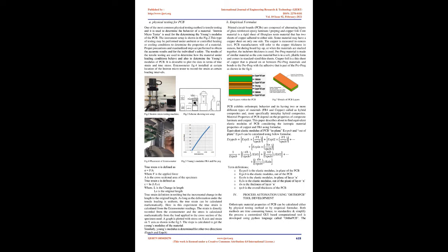The results of the tensile testing are used to determine how the material behaves under loading conditions and also to determine the Young's modulus of PCB. It is desirable to plot the data in terms of true strain and true stress. Extensometer, Figure 4, is installed at a certain location of the Instron microtester to record the strain at certain loading intervals.